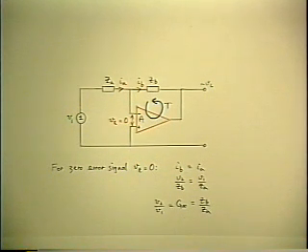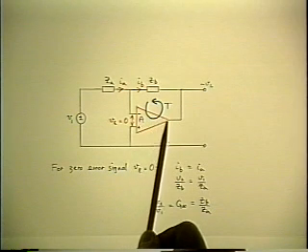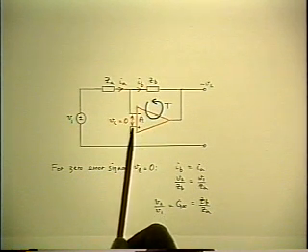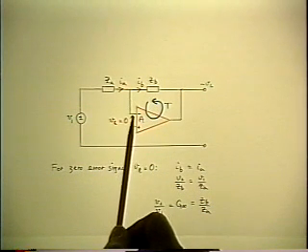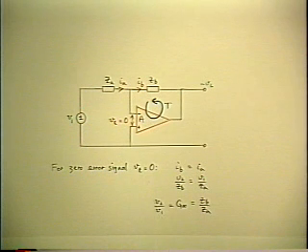One little side point about this, which we'll come back to later on. If you assume infinite gain of the forward path, this says that the error signal is vanishingly small, which says that the error current is also vanishingly small. And that requires no assumption to do with the input impedance.